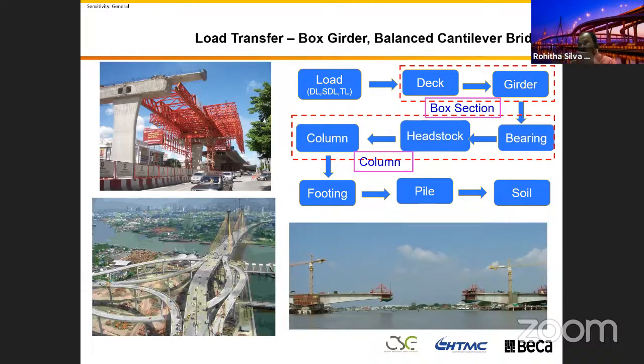But the initial investment you have to place in this bridge is significantly large because of the construction cost. I'm not sure how it is done around the world, but the contractors estimate the cubic meters of concrete, and that's how they price. In payment terms, they might say pile costs this much, column this much, footing this much, girder this much. There are different arrangements, but when costing, they put the additional formwork system and all those things in their overhead.